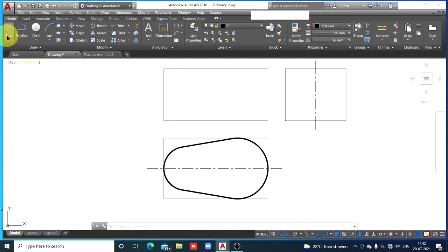Now to establish center, you are going to draw center lines also. So here, check here. When you move cursor to the larger curve, computer is showing us the center for that larger curve. Check. So move cursor to the center. Don't click it right now, because if you click it, a line will start from the center. We don't want a line starting from the center.